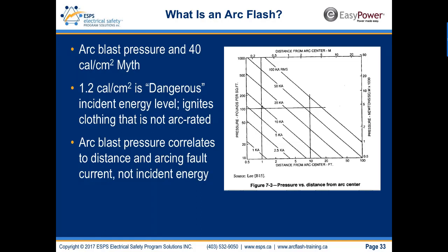Unfortunately, this misunderstanding was exacerbated by the power engineering software, including the hazard risk category tables to correlate to the incident energy results to define PPE, and that wasn't technically correct. All of the software has now removed that correlation between the results table and an HRC, because PPE is not stipulated by a hazard risk category when you do incident energy analysis.